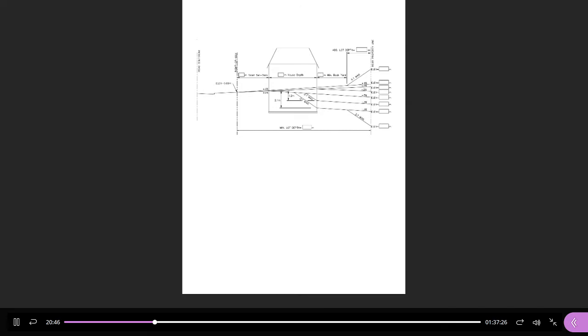Okay. So here's what we're going to do. Let me just explain what this is, and then we'll start. I'm going to sketch all over this, but really we only need to type in. So the first thing you're going to notice is right here, this is the center line of the road. This is half a section. So there's the center of the road, there's the gutter, there's the street line. So we're only looking at half the section. Then what we look at is the front of the lot, where the road is, and the back at the limit of the subdivision. Okay, so that's the front, that's the back.